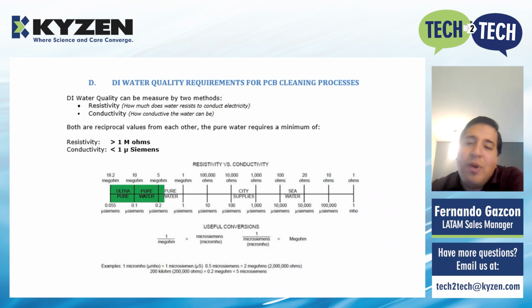As you may already know, DI water is usually obtained by filtering it through a combination of carbon and resin mixed beds. Carbon removes the organics, and resin mixed beds remove the ionic residues. Foaming in the water is related to organics being present in the water. So the foaming issue was probably related to the carbon beds in the water treatment system.